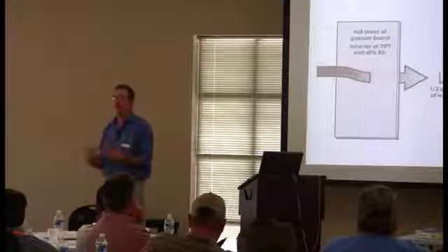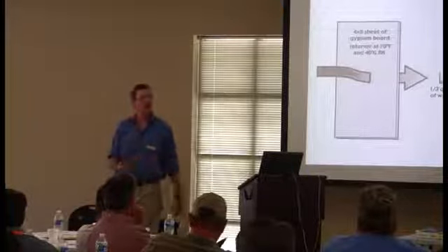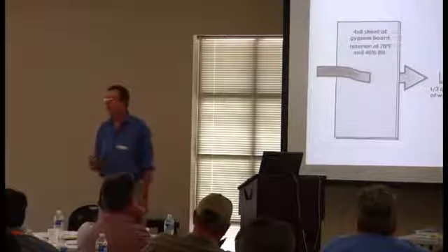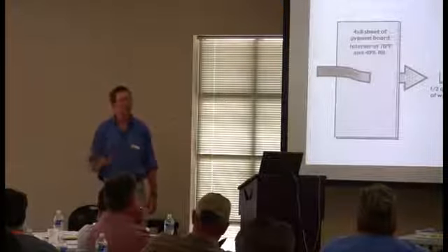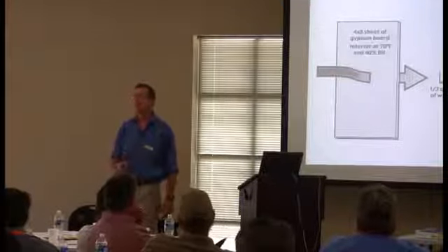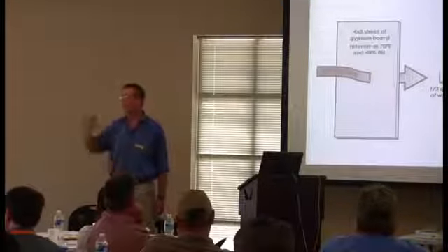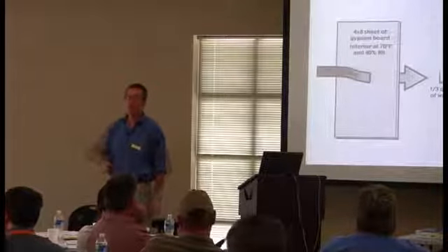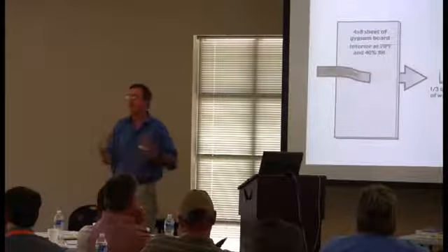Well, that would be correct for us in the winter, but if we were to put a vapor retarder on the inside of the wall, it would be the wrong side of the wall in the summer. Because where's the moisture in the summer? It's outside. And where is it cooler and drier? Inside, because we air condition.